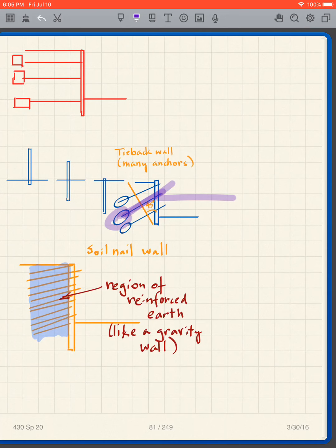And we grout at the end and then insert a rebar, for instance, and that gives us the anchor, and then we basically tie it off here at the wall. And then we excavate some more, and then we do some more. Put in the grout. The grout is usually like a cement, and then you can test these by pulling on the anchor, make sure everything works right.